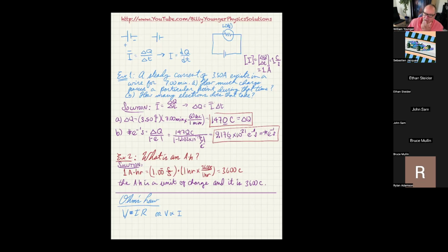If you exceed that 0.25 watts, then the resistance is going to be quite different from there on out. Okay. Any questions on that? Now, the other formula I'm going to remind you of is that when you have resistors in series, the equivalent resistance is R1 plus R2 plus ... plus Rn for N resistors.